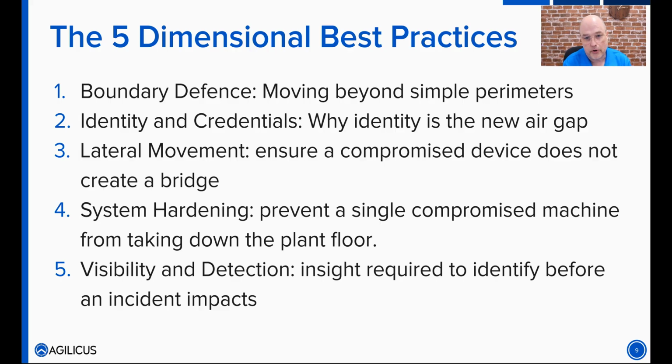The second one's a little bit harder. This is IT stuff in a different building, but it directly supports the process. So I think your SCADA historian here, right? It can't be down. It doesn't run the real-time control system, but you can't have it down. You have to be able to report this stuff. You're going to have to keep it up to date, but you're going to have to do that in some balance between auto updates on Patch Tuesday, which is clearly not in your interest, versus, well, every leap year of a century, but not of 400 years I do it, which is sort of what a lot of you are doing now. So you're going to have to do some work there.